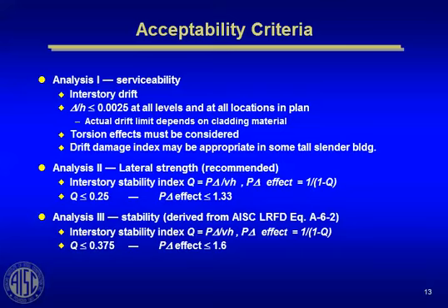I know there are some engineers that say, wait a minute now, these drift ratios all came about 100 years ago in Chicago and New York, when they designed for 20 pounds per square foot above 100 feet, and that's when 1/400 was born. And so that was all based on a first order analysis, so I'm going to do mine based on a first order analysis.